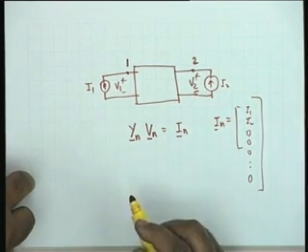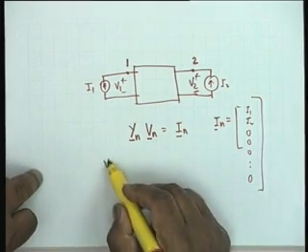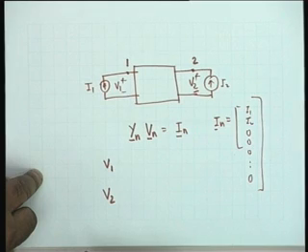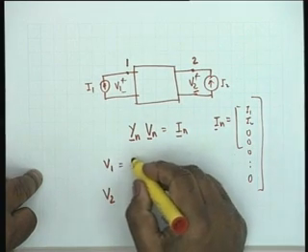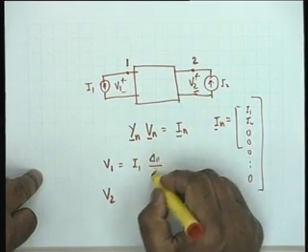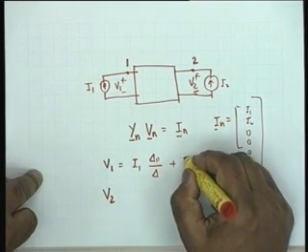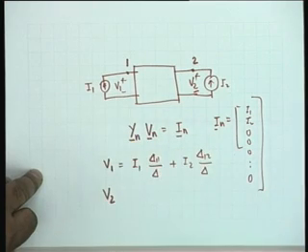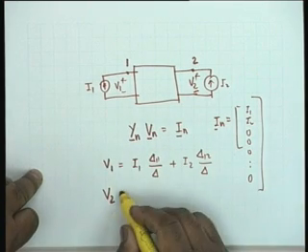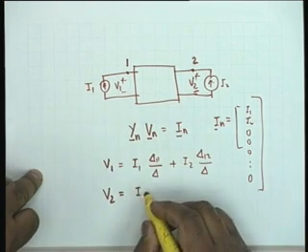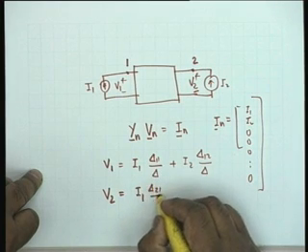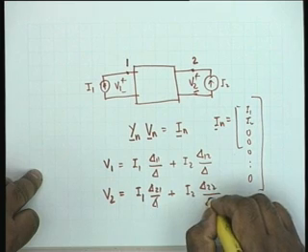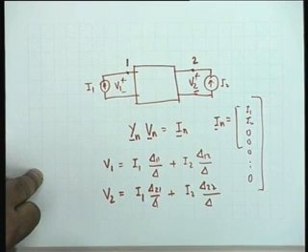Alright. And what we wanted to find out is V1 and V2, that is these two voltages. I want to express them in terms of I1 and I2. And you recall that V1 was I1 del 11 by del plus I2 del 12 by del, where del is the determinant of this matrix. Similarly, I have done this earlier, V2 is I1 del 21 by del plus I2 del 22 by del. Agree?